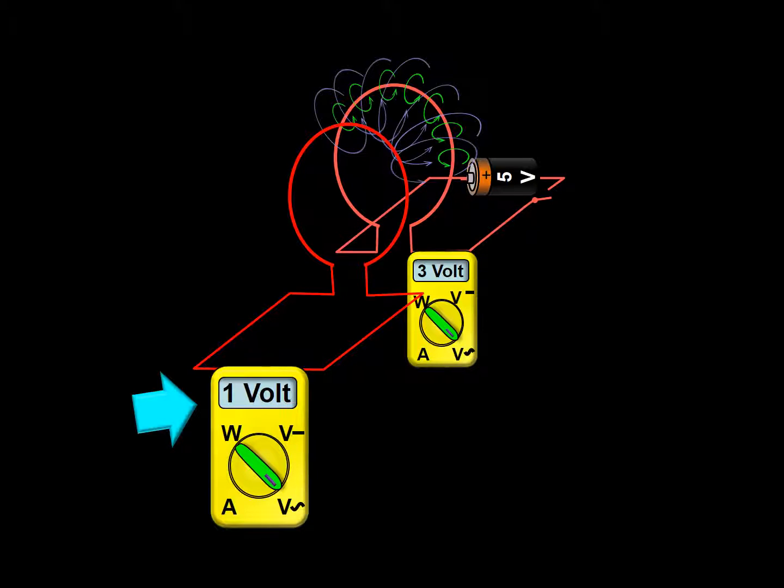The only difference in this frame from the one before is that the magnetic force of the primary circuit has created a voltage in the secondary circuit. This is reflected by the voltmeter in the secondary circuit going to 1 volt. This frame introduces a magenta arrow to indicate the current arising from the volt just created in the secondary circuit.